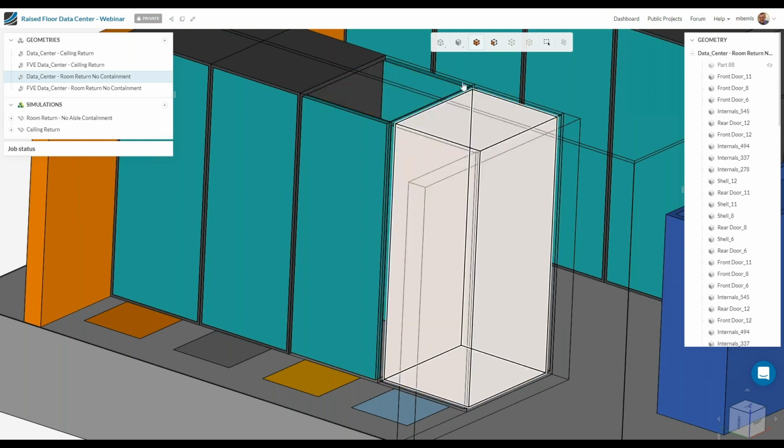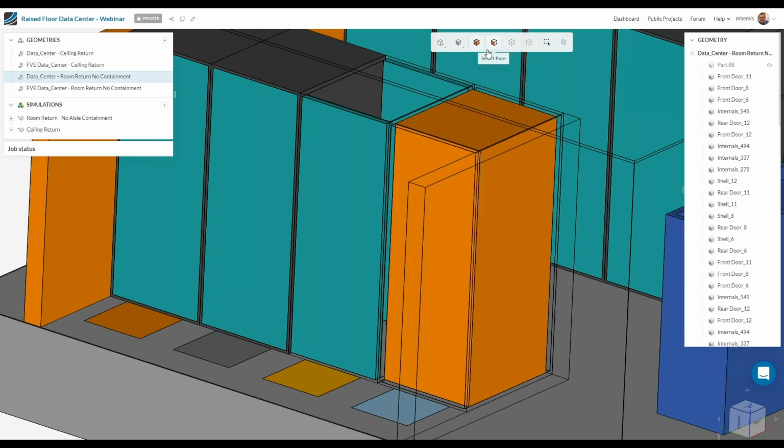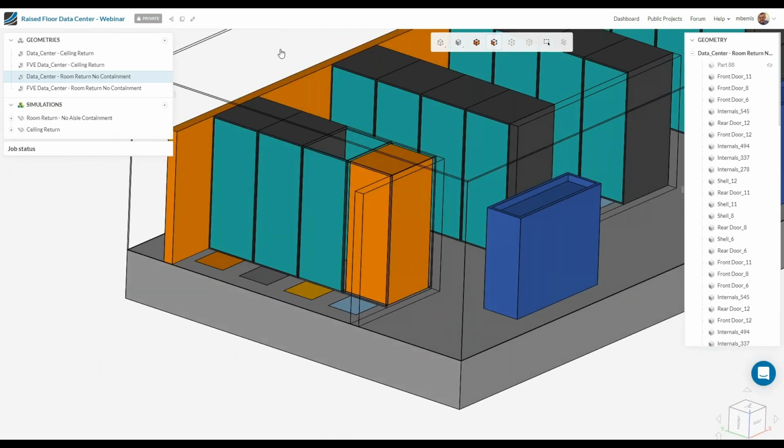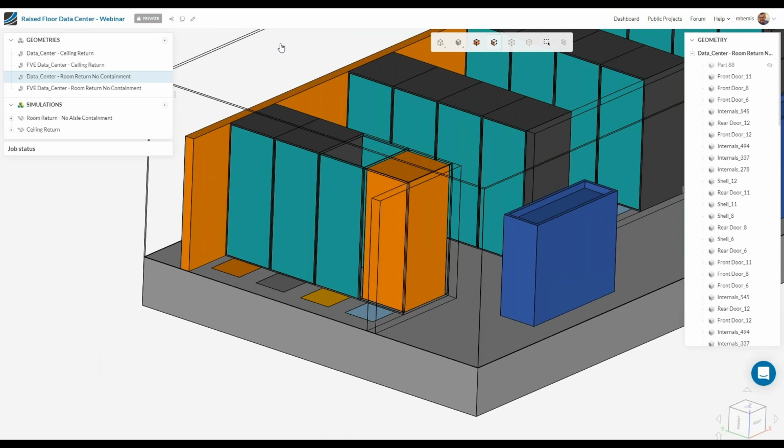I'm not actually going down to the U level. The way most data center modeling is done, is we're going to say there's a uniform 8.4 kilowatts on this rack. It's not how everyone does it, and SimScale certainly supports going down to the U or 2U level, server level, but it takes more time to set it up, and requires more information too if you're using DCIM tools to pull that information. It becomes a lot more.